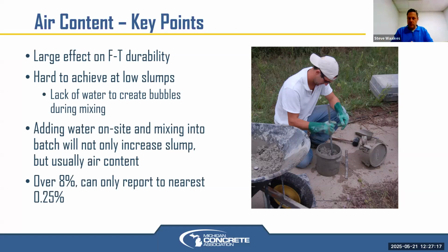It's that difference between those 2 curves that is the SAM number. It's a measurement of the stability of the air content from those 2 different cycles. So 3 times the pressure, 2 full cycles, so 6 pressure tests on the exact same bucket of concrete.